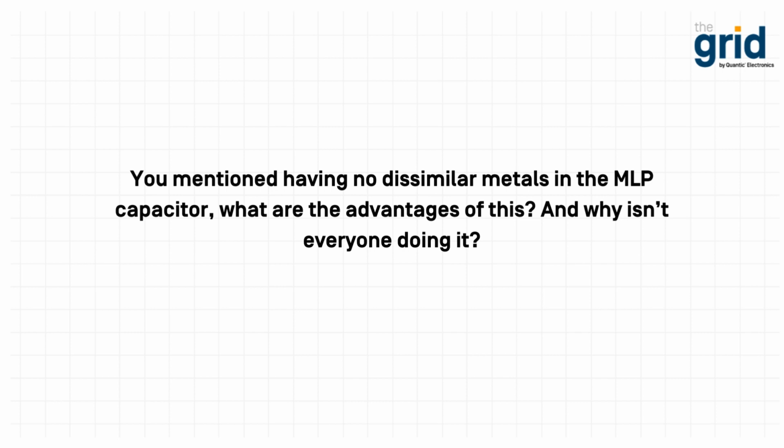The unique construction of our capacitor allows for pure metal aluminum terminations to be used. And by using aluminum terminations, we don't have to have any dissimilar transitioning metals to reduce galvanic corrosion within the electrode itself. The reason we can use that where others can't comes down to the stack technology and the way that we actually stack the capacitors in a group as we metallize the outsides of them to create the terminations. So again, very different process that allows us to create a much more high reliability product.